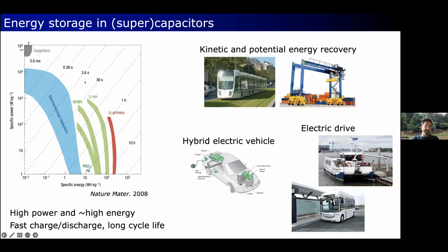So they have a relatively high power compared to batteries and relatively high energy compared to standard capacitors. Also, what is important to notice is that they can be charged or discharged within seconds. And they have a long cycle life, which means that you can charge and discharge them many times before the performance starts to deteriorate. So they are used in specific applications where you need a high power, so fast charge and discharge.